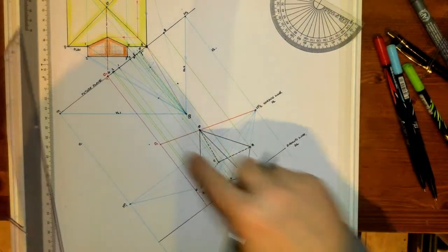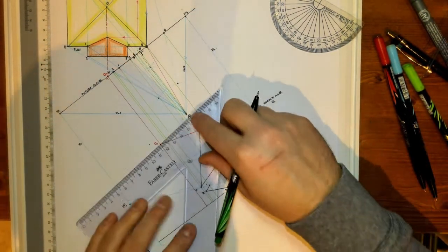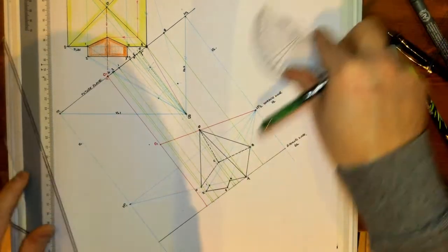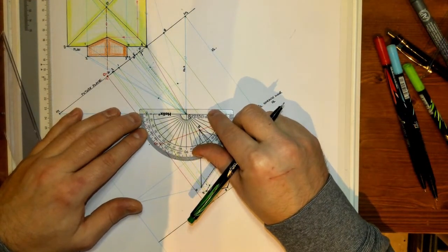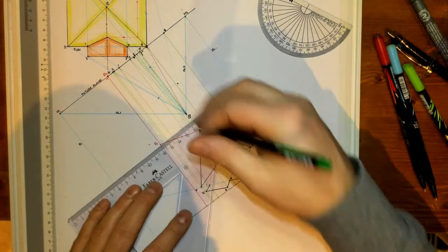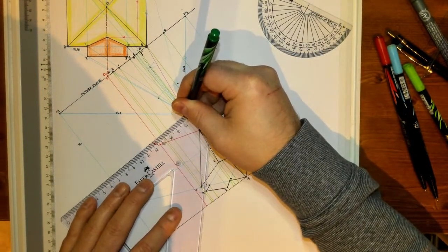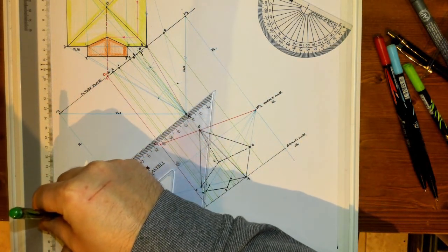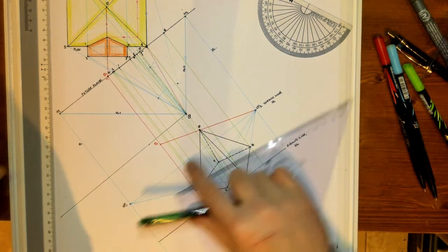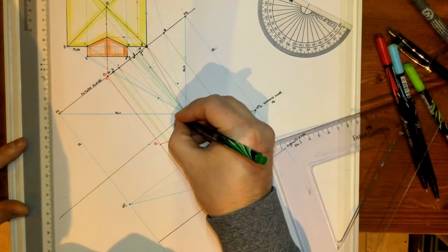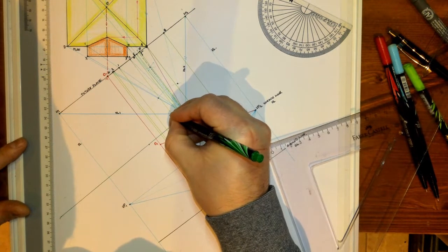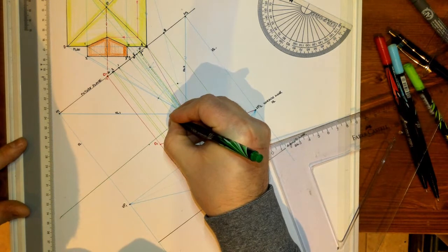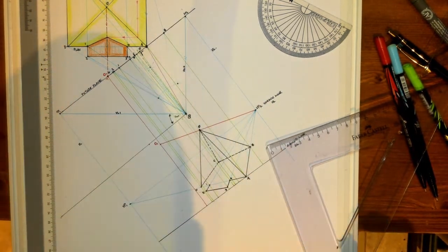That's the angle of this surface, the orange surface in the elevation. Okay, so 40 degrees, and from S, I just want to double check that that's 40 degrees. Yes, it is. Happy with that. From S, I'm going to draw a line now through that point, and I'm going to extend it on. So you can see that line I've drawn now. Okay, we'll put 40 degrees, and we'll just indicate there that the angle is contained between vanishing line 1 and the line we just drew.